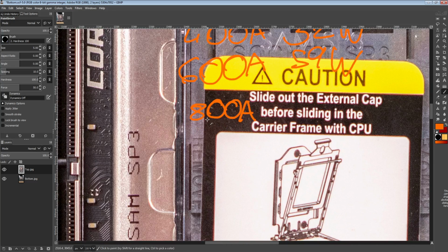And for that, you'd be looking at a 64 core running over 4 gigahertz at 1.3 volts. That would be in Prime95 small FFTs, which is a kind of ridiculous worst case scenario loading, but it should theoretically be possible because an 8-core CCD Ryzen 3rd gen under small FFT Prime95 at 1.3-ish volts, it doesn't need to be exactly 1.3, will pull around 100 amps.